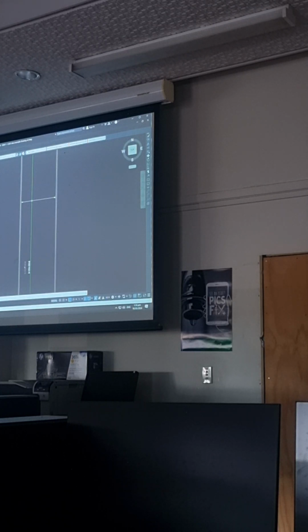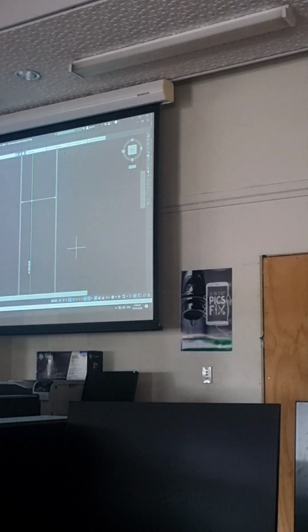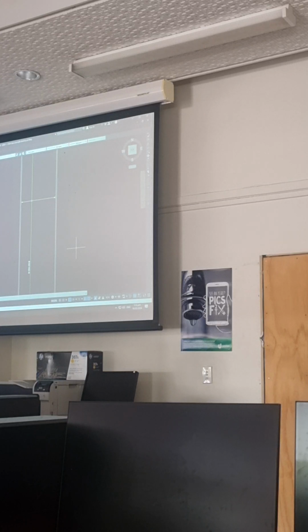First of all, your bar schedule will have counted all the bars at one end and all the bars at the other end. So your bar schedule will have twice as many bars as you're going to be calling up on here. So if there was 18 bars on your bar schedule, you'll be calling up 9 and 9. If there was 100 bars on your bar schedule, you're calling up 50 and 50.